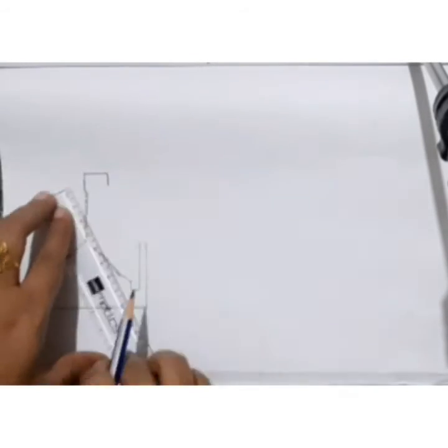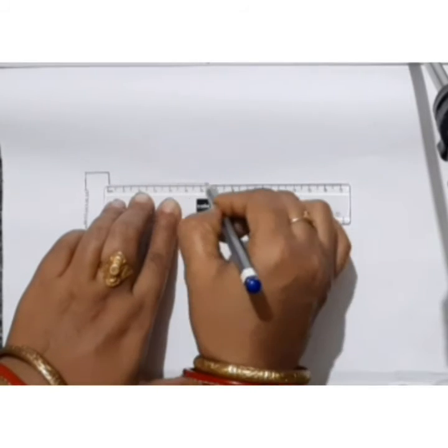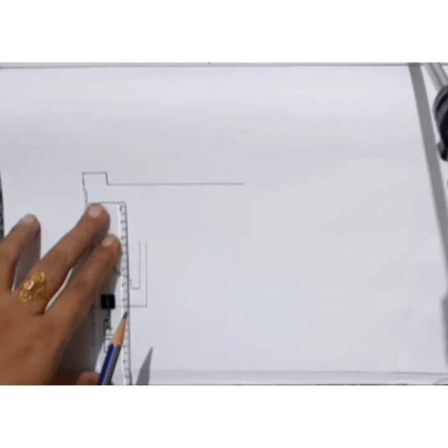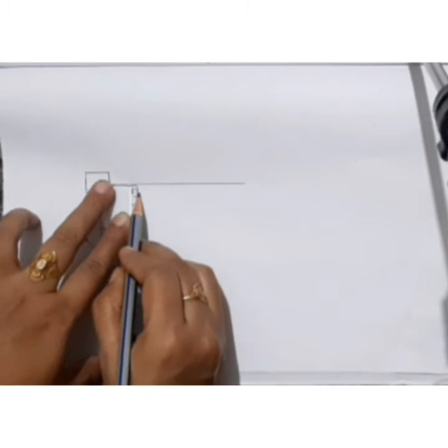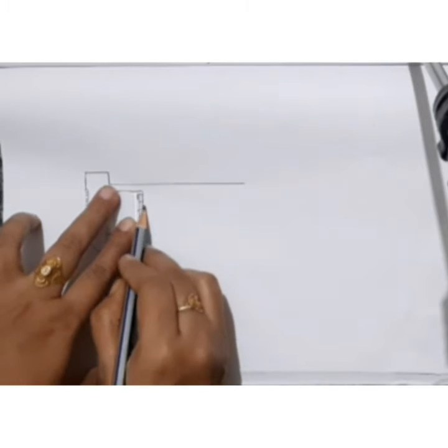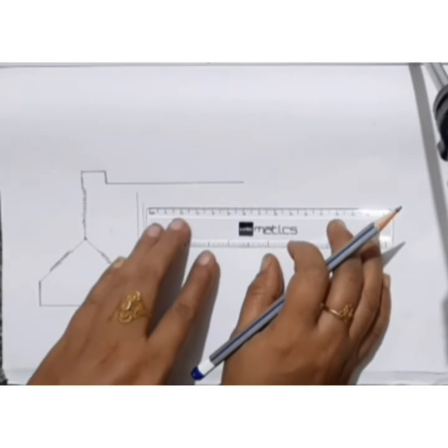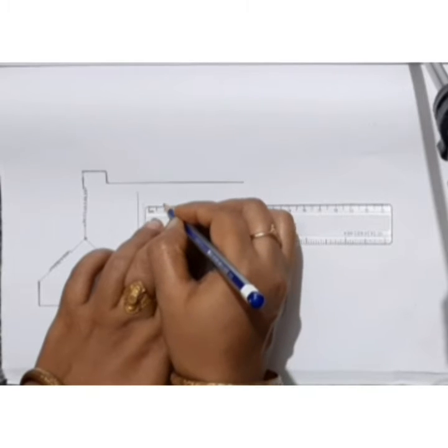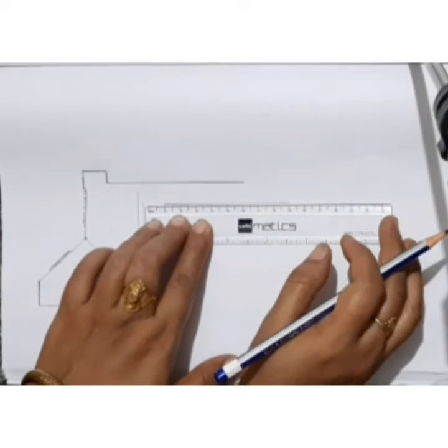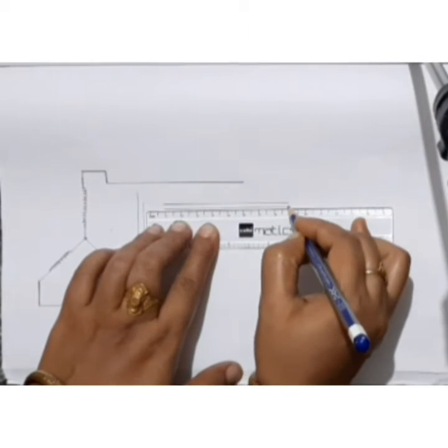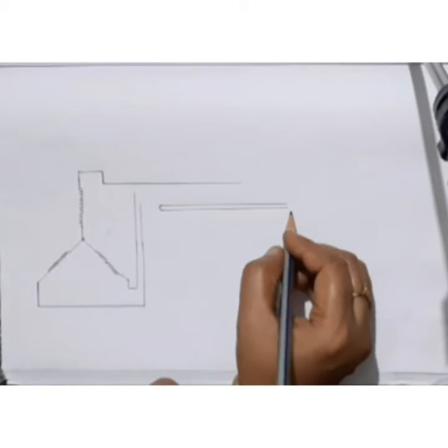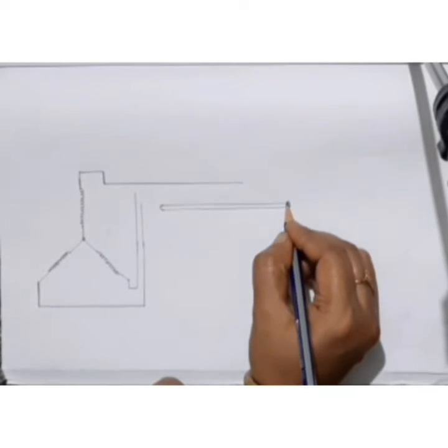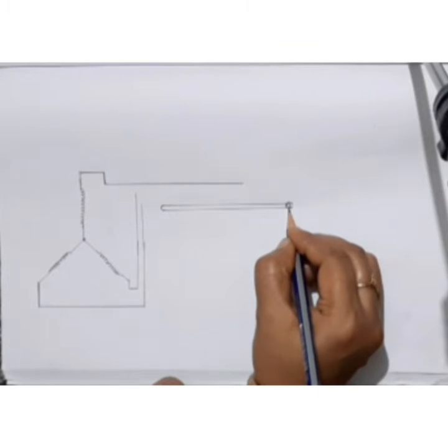An auto transformer starter with necessary arrangements. Such starters consist of auto transformers with necessary arrangements. At the time of starting, a reduced voltage is applied across the motor through the tappings. Here in the diagram we will also show the tappings, and the motor gets a lower starting voltage according to the selection of the tappings. The motor also draws less starting current and develops less starting torque accordingly. When the motor attains 80% of its normal speed, the auto transformer is cut out of the circuit and full voltage is applied.